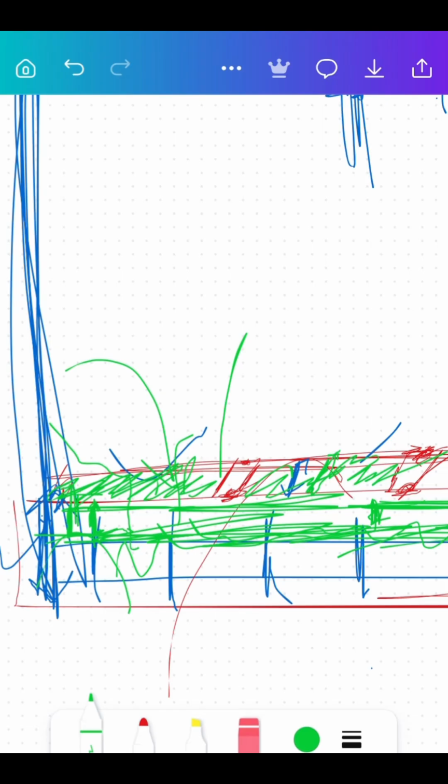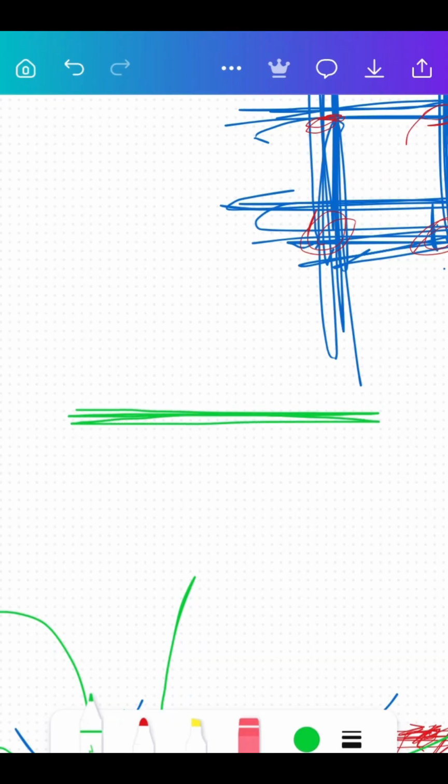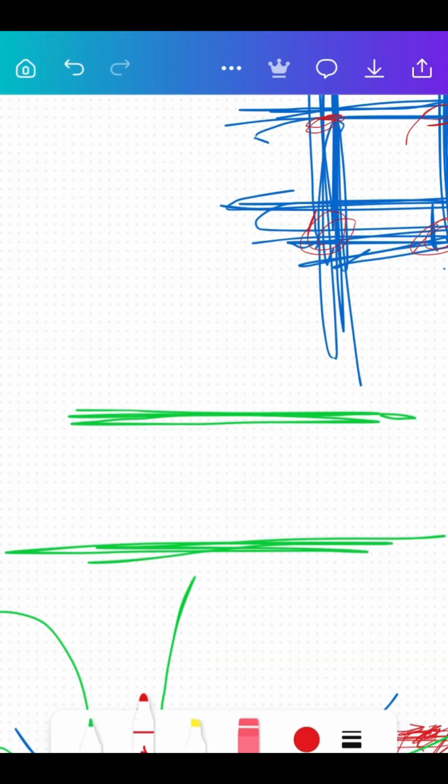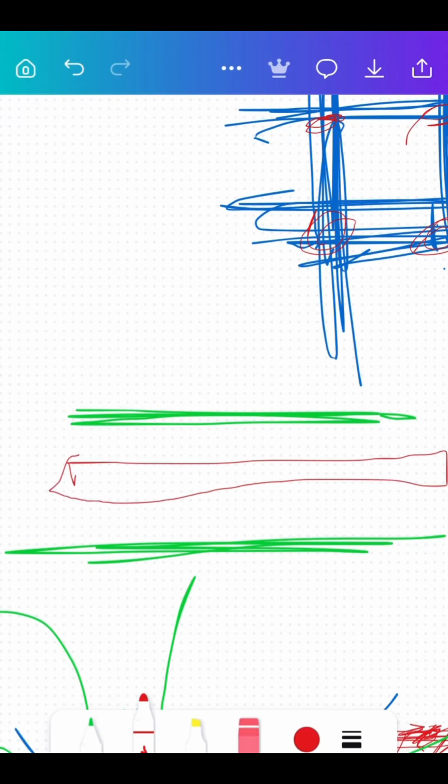And remember, this polystyrene is going to protrude out just a little bit. The polystyrene is going to be flush with the top of the concrete. Because it is from the top and it goes down about 12 centimeters. So at least we'll still see the top of the polystyrene. So it's going to look something like this. If you're looking at the top view of it, you see the polystyrene sheet in the middle. At this point, the iron has already been submerged in the concrete. You will now have the concrete on the side like this, now flat on the top.